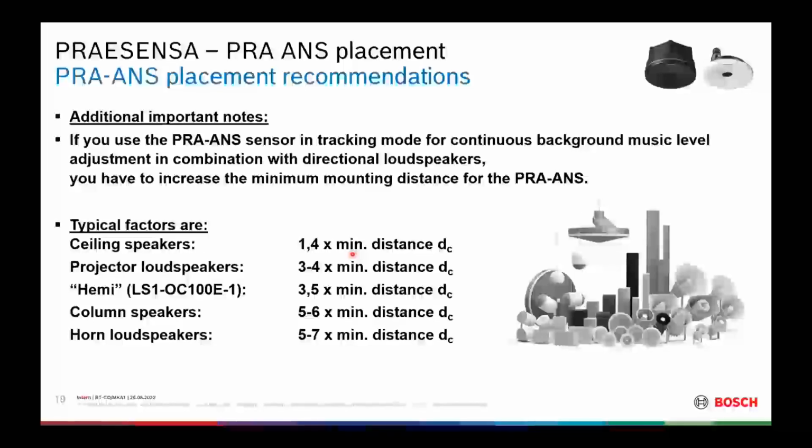If I have a projector loudspeaker which has even a little bit higher directivity, meaning my direct sound field goes a little bit further, I have to go a little bit further away to come into the diffuse sound field, meaning I should stay away 3 to 4 times the minimum distance which we saw on the chart before. The Hemi is also in the same category with about factor 3.5.